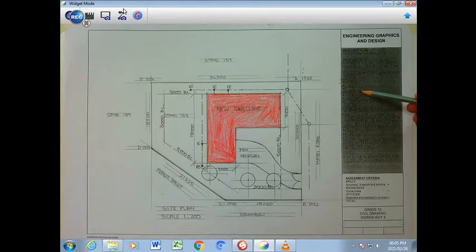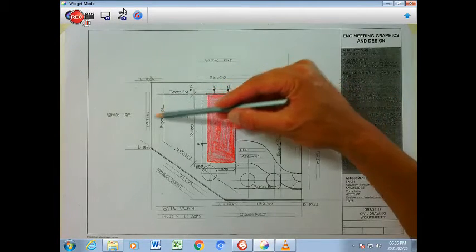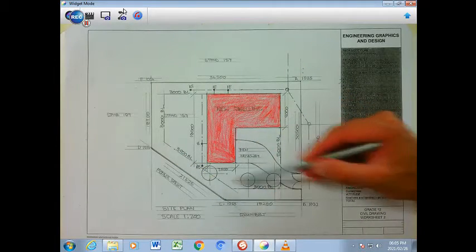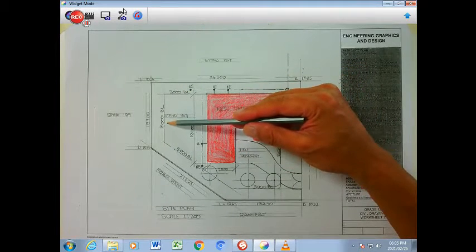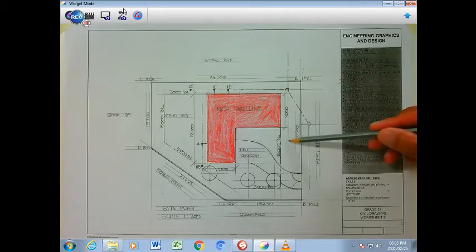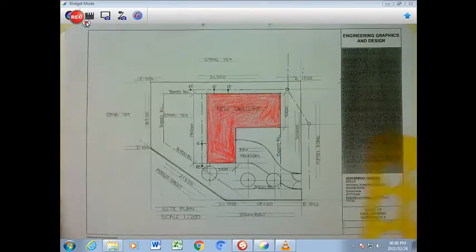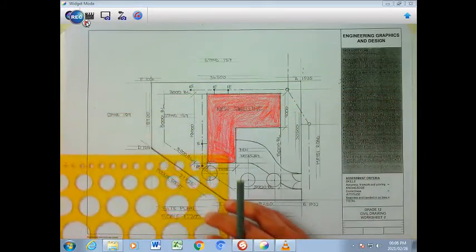We're looking at the building lines. The building lines are the required distance away from the boundary line. As we can see here, 15 all around. If you scale that by 200, 3,000, which is 3 meters, and in this case here you have 25 for the 5,000. And then we have our north point, which we don't have, so we're going to include the north point quickly. That is one thing that we don't have. So all we basically need is to find a little blank spot and any size of your choice.